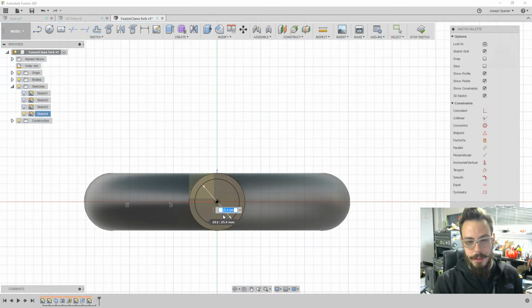One thing that we can do is, if we were flip-flopping on units, but I'm currently working in millimeters, which is in my model tree here, I could say this is 1 inch or inch and hit enter, and then it will convert the units.